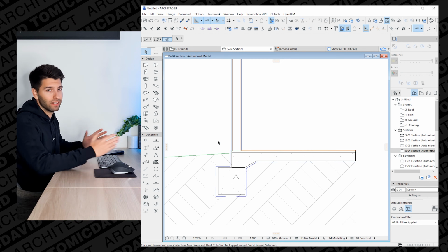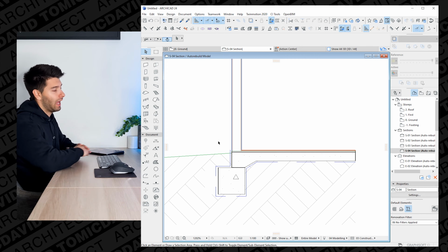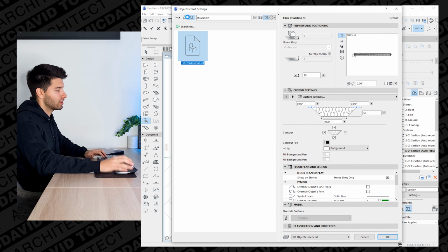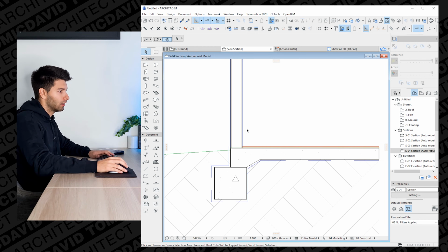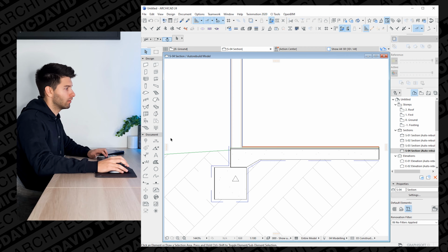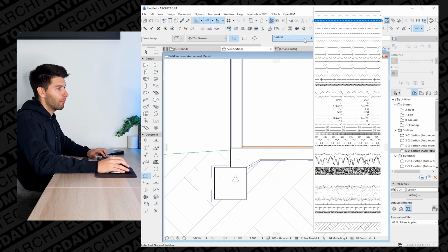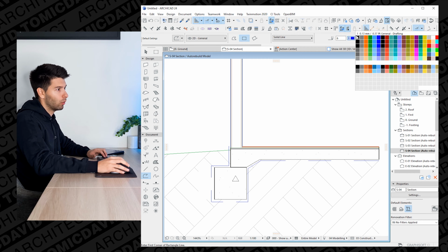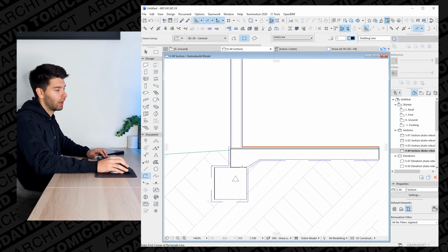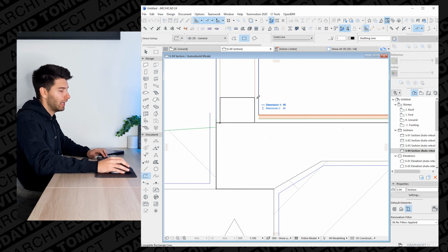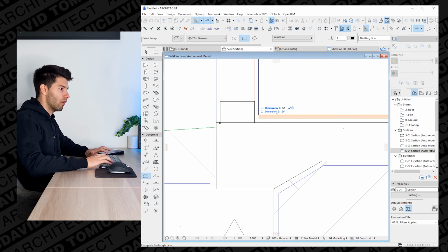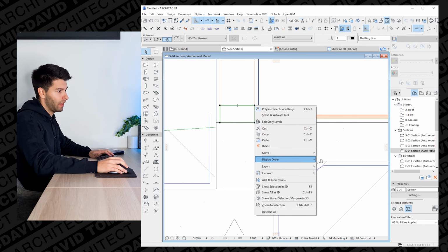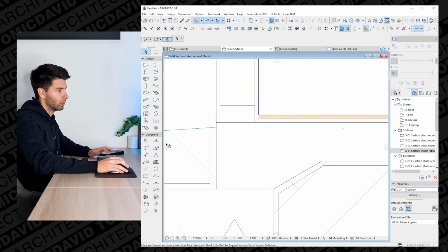What we do is basically have a series of timber battens, and along the bottom we would have our base plate. So if we come across and type in stud, now what would happen in this situation to the bottom of that timber floor is we would have a bottom plate actually sitting on that floor. So I'll change all of these settings here to square, solid line, black, and we'd go ahead and draw a 90 by 45 timber frame. Let's bring that to the absolute front so we can see it.